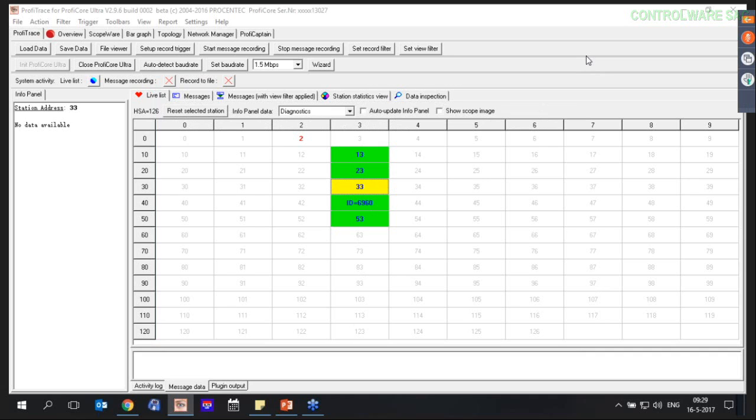There was a really good question. We get this question a lot of times. There is a termination on your tap connector, and the question was, does the termination need to be on or off? Well, normally when you just use Proficore, it should always be off. The reason we keep this termination in is that you can use it to see where your device is.